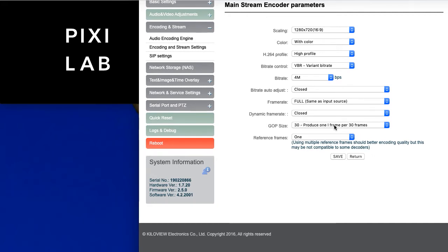And here I've set it to a fairly conservative 30 frames GOP structure, which means there's a single keyframe per every 30 frames. And this is a 30 frames per second camera, so there will be a GOP size of about 1 second. So that will give some amount of delay, and let's start looking at that, and then we can tweak these as we try other settings later.